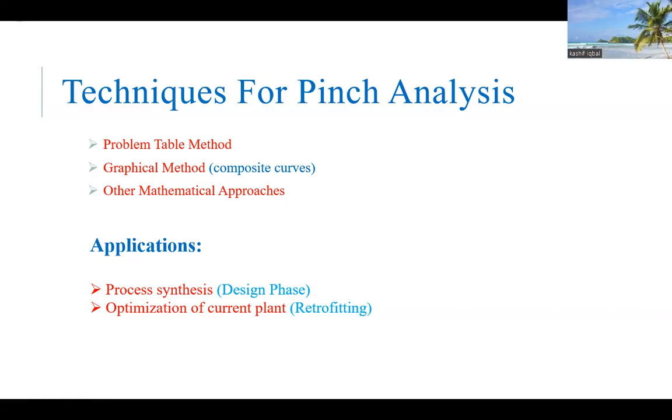So when we talk about the application of the pinch technology, nowadays it is defined for the process synthesis and the optimization of the current plant, which means that we can retrofit the plants that already exist. In the process synthesis, we can make the flow sheet, we can size our equipment, and after sizing the equipment, we define how much energy can be recovered in the newly designed process. But in the retrofit approach, we basically optimize the process that is already defined, and at the time it was defined, we didn't optimize that process for energy recovery.